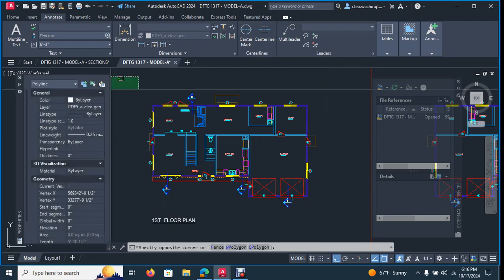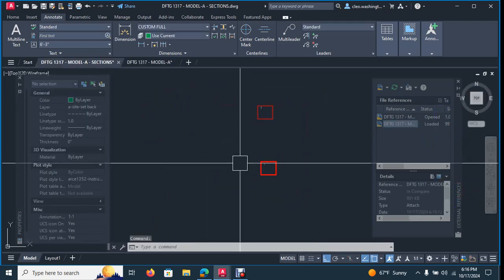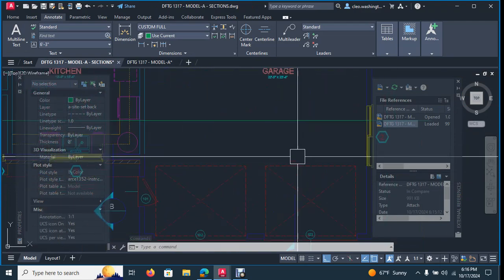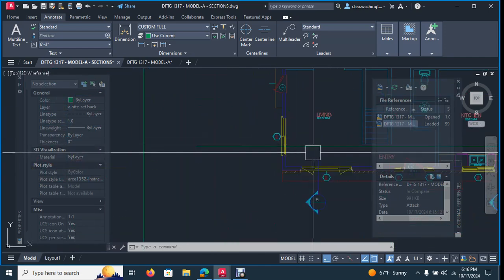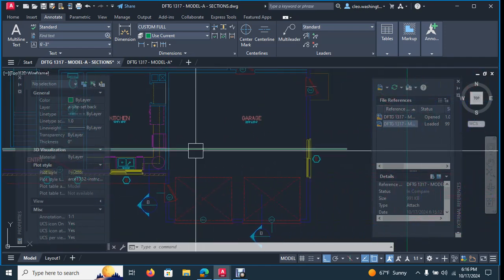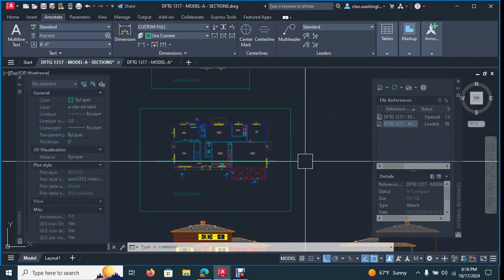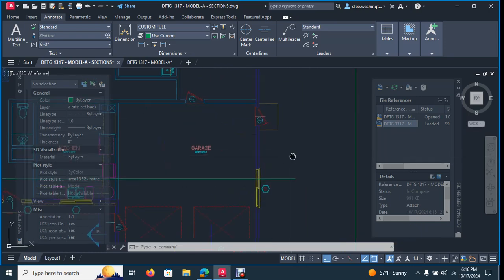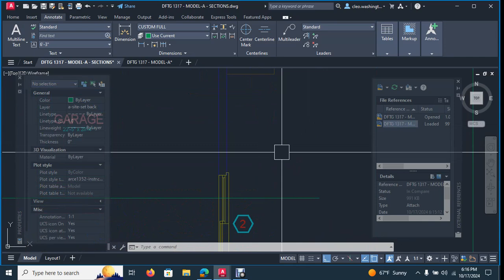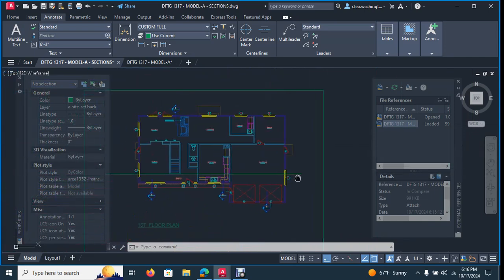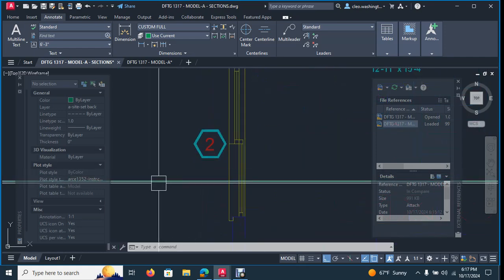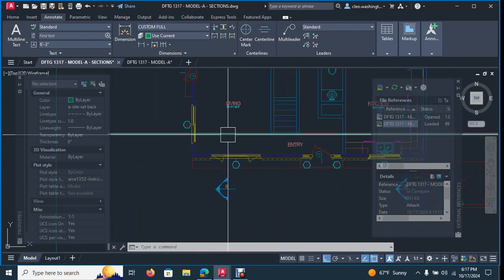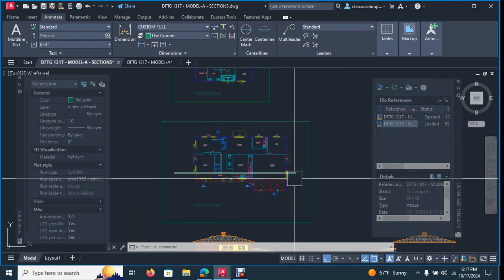Everything else seems to be siding. So if you actually draw, and let's go back to the section drawing. If you actually draw a section cut, okay, you have a window here and you have a window here. You have some interior walls here. You have the kitchen here. You're actually not showing what the exterior wall looks like at the siding, okay? You have the exterior cut at the window, and you also have an exterior cut at the window here. Well, that's a little bit redundant. Contractors only really need to see it once as per any given section.